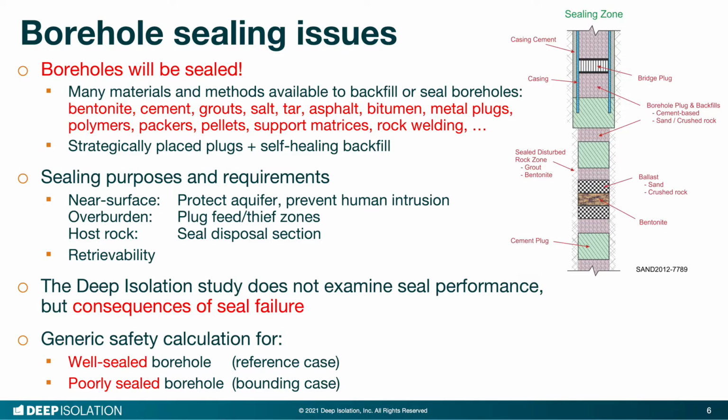The poorly sealed case does not assume that the borehole remains open for 1,000,000 years, but that its backfill or seal has crumbled or is cracked or detached from the borehole wall or otherwise degraded to the point where it has a permeability of beach sand. Sand would pose little resistance to contaminated water being pushed up the borehole.